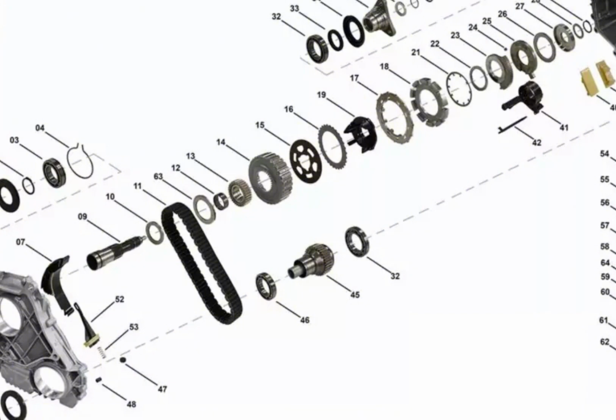Test the valve body by manually shifting through gears. Use a photo if you're not fully sure, and take photos as you go along. Step 5. Installing the transmission back into the car. Attach the transmission to the engine and secure with bell housing bolts. Reconnect all components, mounts, axles, linkage, and wiring.